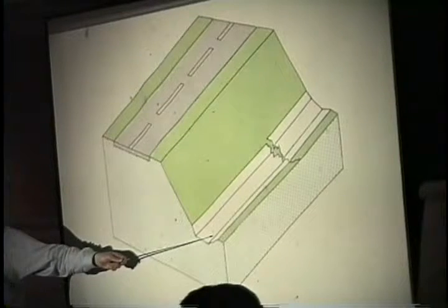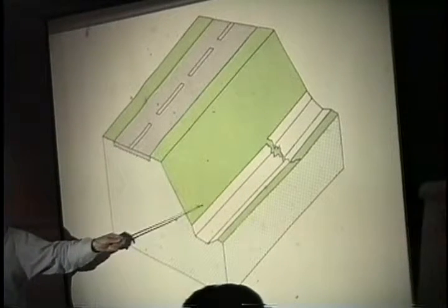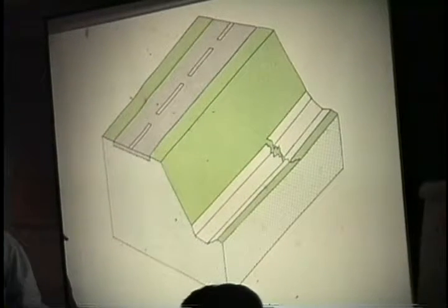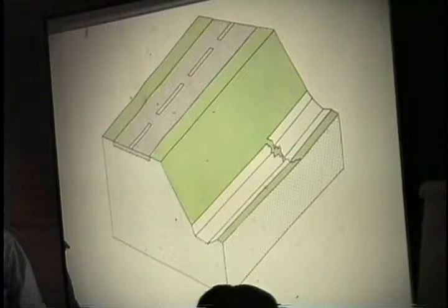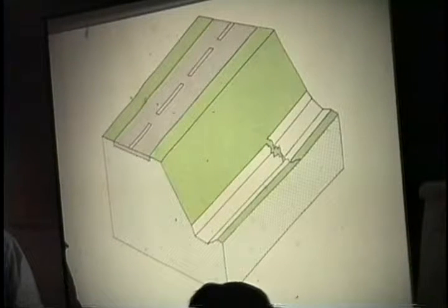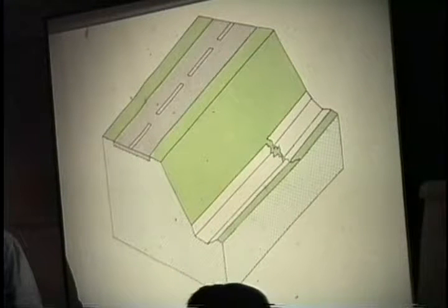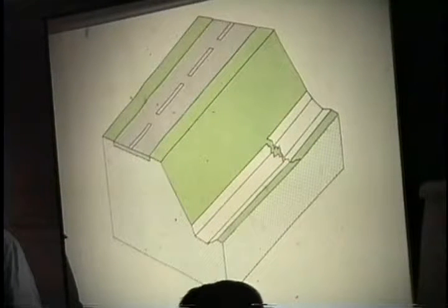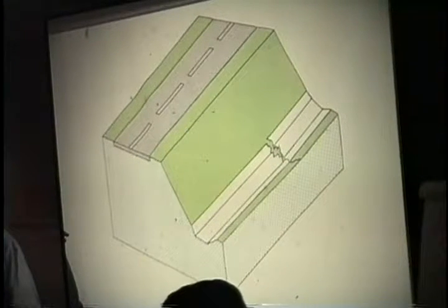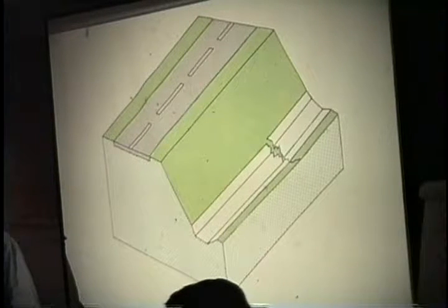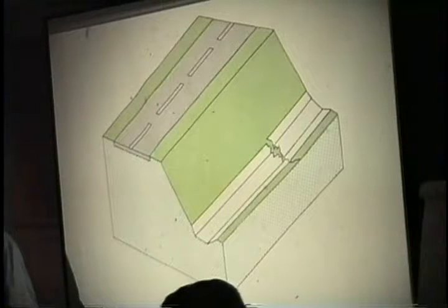First of all, a rule of thumb, a maintenance thing: if this ditch is pretty steep on the side of the road, how would you modify it? You still want to put riprap. How would you modify the riprap? Finer or smaller particles, or bigger? Bigger.